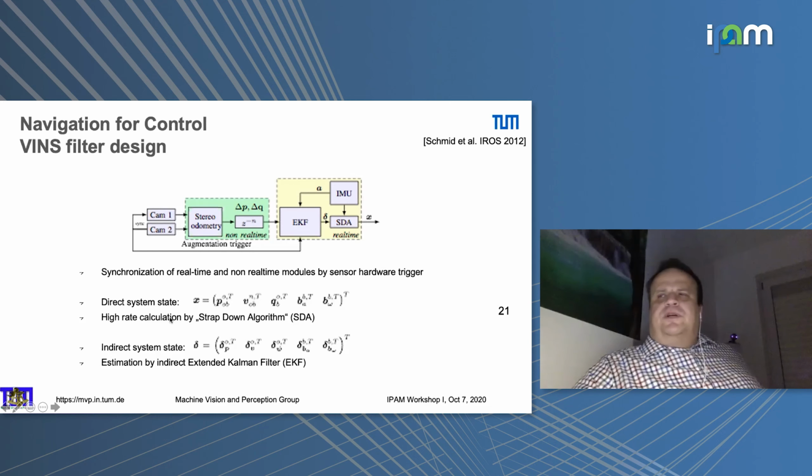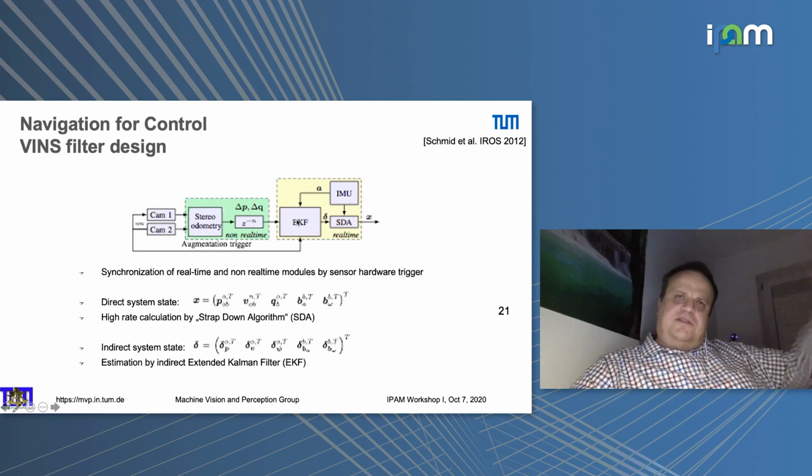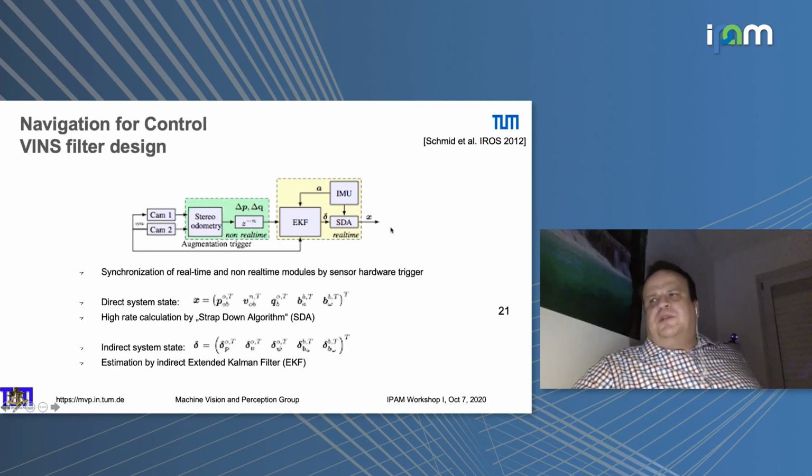And the only way to do it is actually to switch to a system which is not based on the camera, but it's based on inertial units. So it's taking an inertial unit, it's integrating the accelerations the system is measuring and outputting them as a position. It's using the camera only to compensate drifts in the IMU. What's the advantage? The advantage is the output here is 30 Hertz. The output here is 1000 Hertz. So I'm a lot closer to my control algorithm, which I want to use.